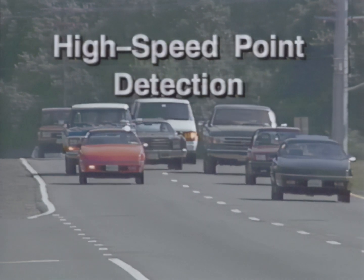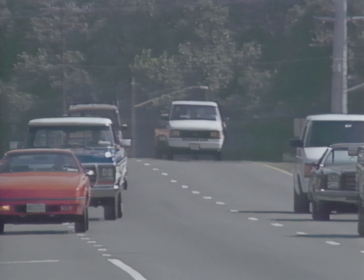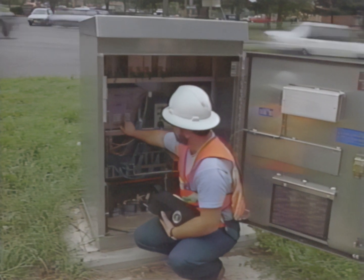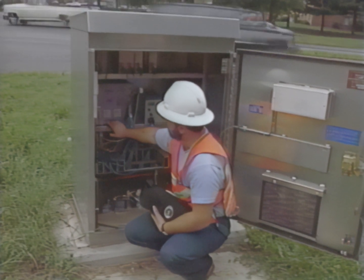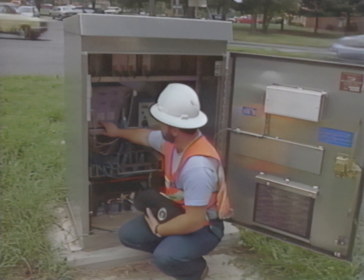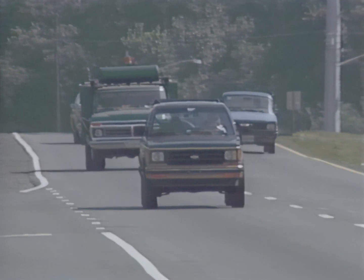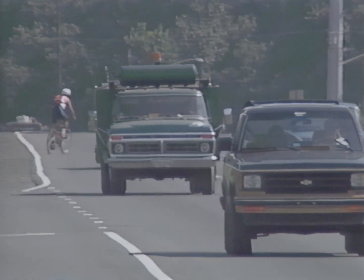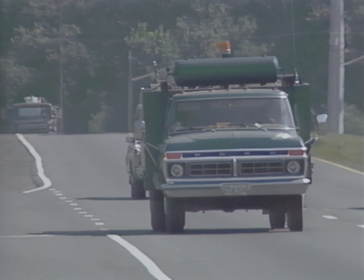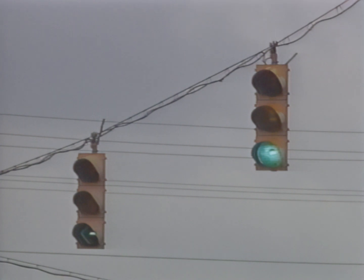High-speed point detection requires a more complex relationship between detector and controller. Volume density control, which relies more on controller function than on a complicated series of detectors, is popular for high-speed approaches. This technique specifies the installation of one point detector per lane, placed 5 to 10 seconds from the stop line. One drawback to high-speed point detection is its potential to place vehicles within a dilemma zone during the yellow change interval.